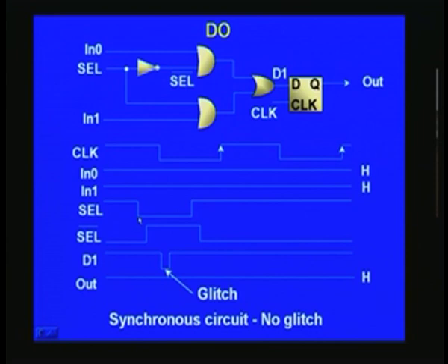So here, of course, there is a delay, and this gate delay is because of this inverter here. If you see the output at D1, what happened? It is nothing but ORing of this, since IN0 and IN are 1 each. So whatever you apply here, that is select bar and select, will appear at the respective ends here, and when ORed you get precisely this. This is caused because you can just see here, this is 1 and this is 0.